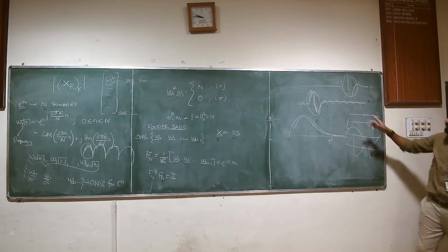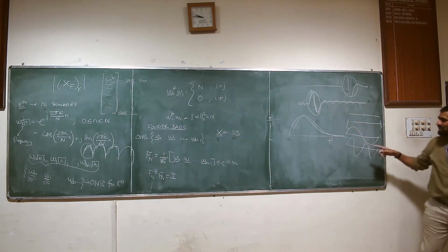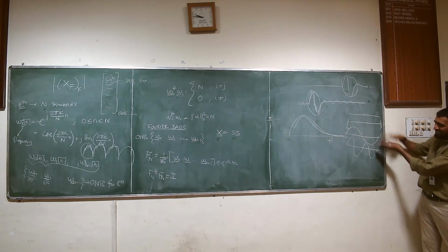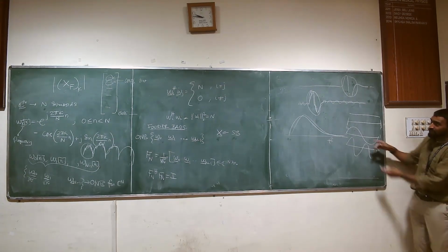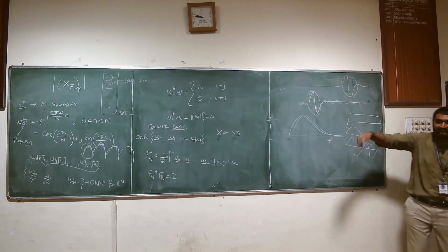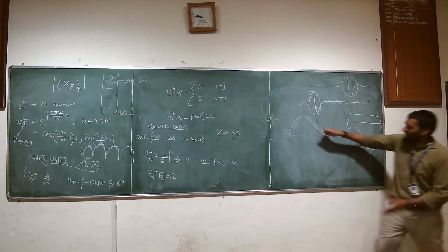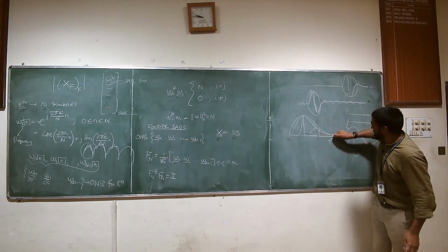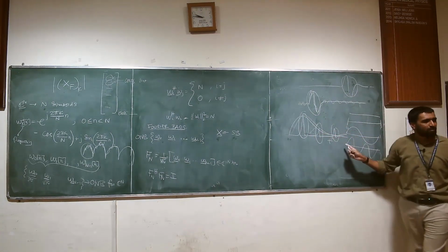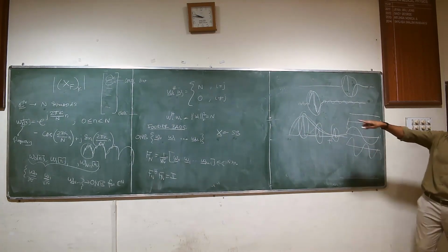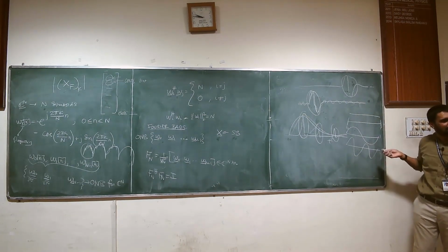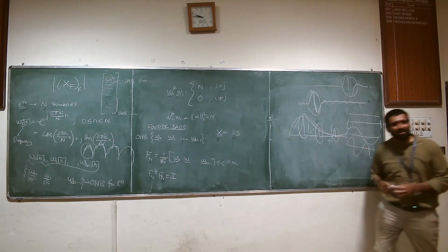That is why if you want to represent something like this, you have to do a lot more complicated scaling of each of these vectors and add them together to get this. You don't have a nice clean representation. Whereas in the previous data, which had a lot of rhythmicity, you had a very nice representation like this, which showed that the signal has these three or four major frequency components. That does not appear here because the signal that we're trying to analyze with the Fourier basis does not look like any vector in the Fourier basis. That's why the representation that you get is not very insightful.